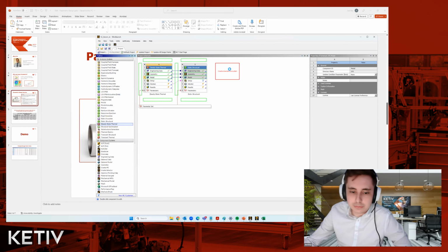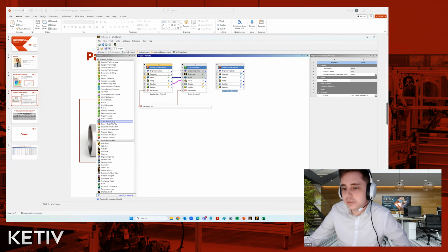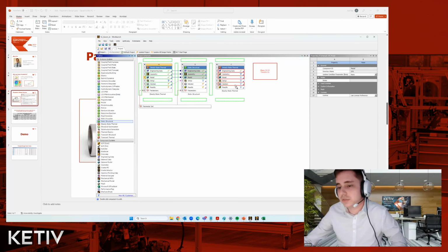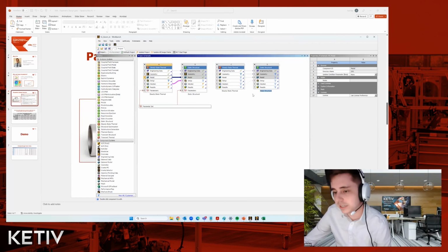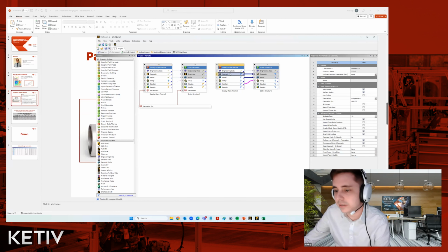And to do that, we just drag and drop them into this white space here. And we're going to link the static structural analysis to the solution branch of the thermal analysis. So what all that's saying is, we might want to consider some thermal stresses here. So we're going to link that static structural to the solution branch of the thermal, because that lets us look at the temperature distribution from the thermal analysis and calculate those thermal stresses. All right. So now that we've done that, we're actually going to just import a geometry that we've already made of the pipe. And to do that, we just import this geometry like this.